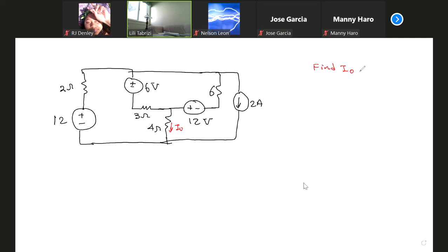Okay, method one, and I have to erase because I don't have enough space here. Usually in class, when you have a large blackboard, you can show all four methods side by side, but here I have to erase. Okay, source transformation. I have to look at the overall look of the circuit. First of all, do not touch the part in question. Keep it, because it's related to the question.